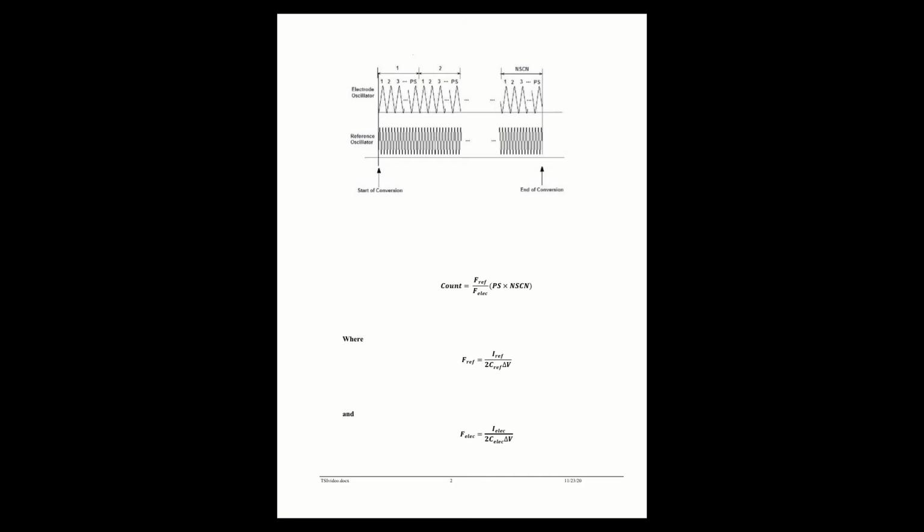And so that frequency is based on the current, on the capacitance, and then the delta V are the two thresholds that are detected to turn the cycle around. So if we reach one threshold down here, we start going up. We reach the other threshold, we start going down. We reach the first threshold, we go up.